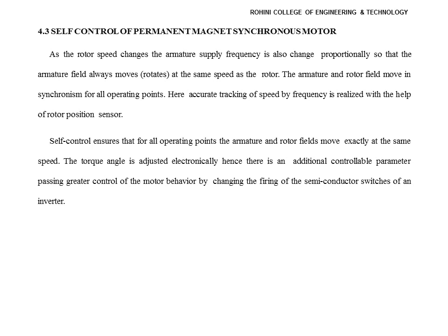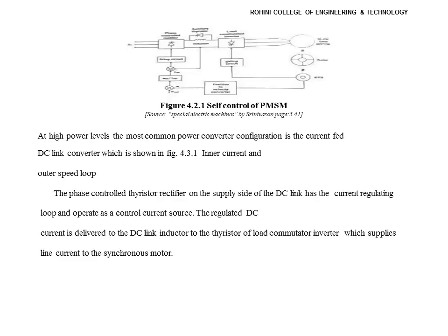The rotor angle is adjusted electronically, hence there is an additional controlled parameter providing greater control of motor behavior by changing the firing of the semiconductor switches of an inverter. This is the diagram for self-control of the PMSM motor.